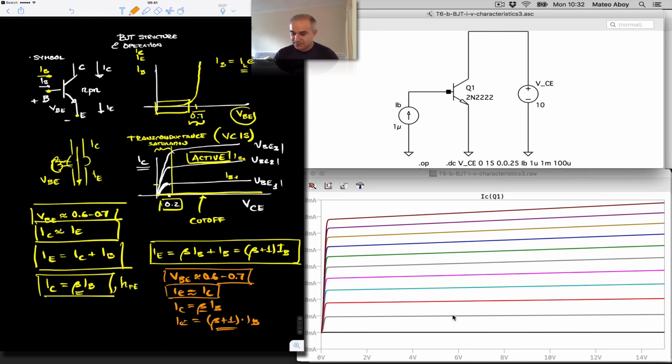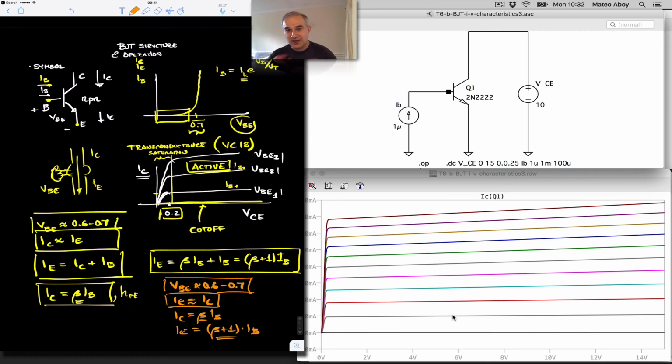So let's recap. A transistor, a 3-terminal device. Because it has 3 terminals, it's going to have different modes of operation. Okay? It's more complex than a 2-terminal device. It can be cut off. It can be on, so it can be used as a switch. And then, even when it is on, it can be on in different ways, depending on the bias. Think of biasing as programming your transistor, supplying DC voltages between the terminals so it works in a particular region.